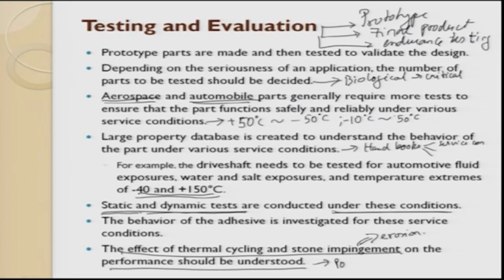Generally speaking, polymer damage resistance is very poor. So this is one area where people are trying to add ingredients and make sure that it withstands damage. For example, a bird hit or a spanner drop on the wings of a plane. In polymer, the crack initiation takes a lot of time, but the moment a crack initiates, the growth of the crack is very, very fast.